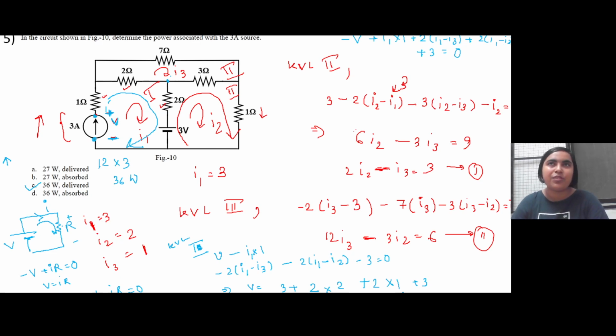Mostly, if you see a lot of parallelly connected loops, so if your circuit looks like something connected, then something connected here, then something connected here, it is easier to use KCL.